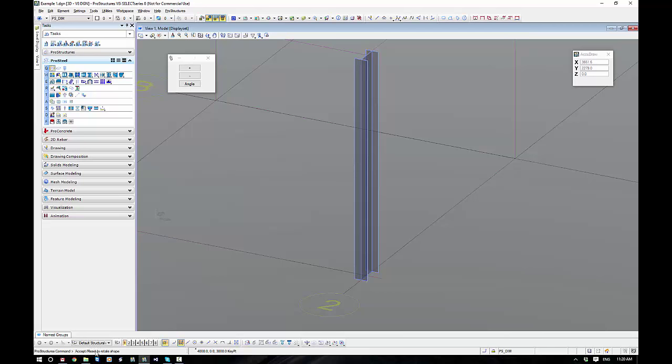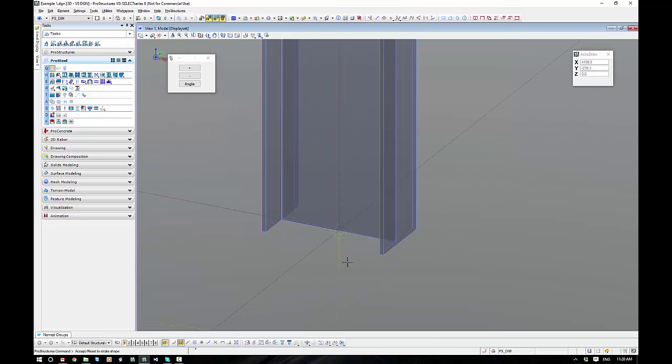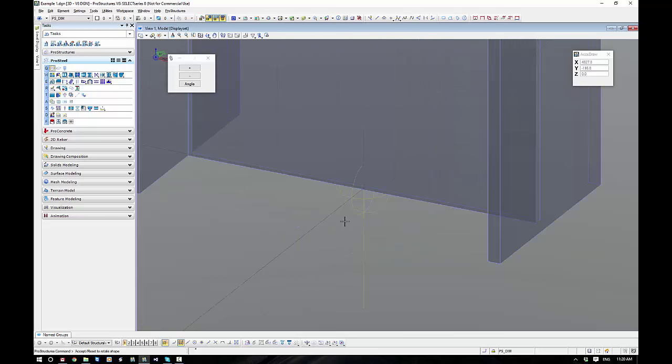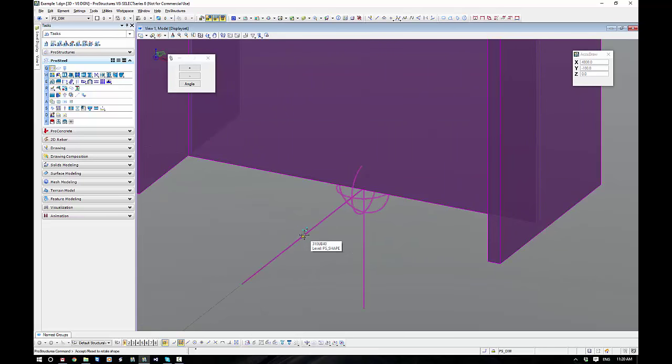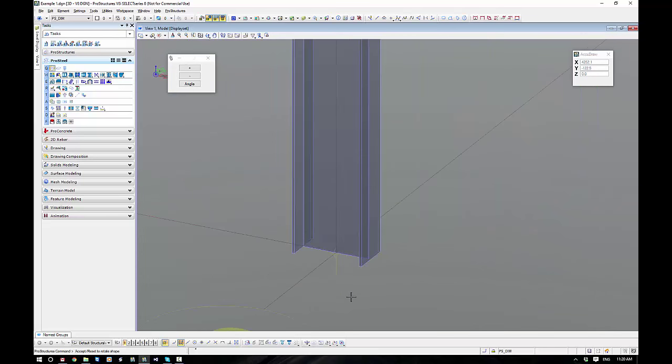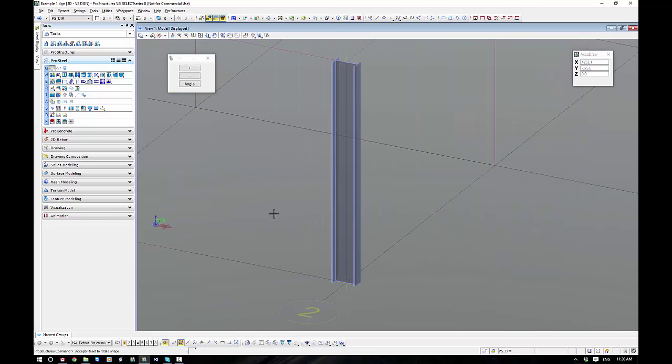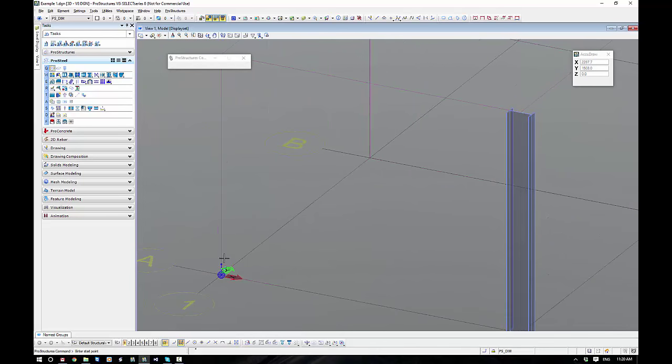Now, accept or reset. Reset is right mouse, remember? So if I want to rotate that, I right mouse click, and it will just keep rotating. Simple as that. It's a little bit hard to see my ECS, but I can tell you that the red line, you can see it there if you hover over it, is the red line coming out. You will get the hang of where these are, which means the blue line is going off to the right.